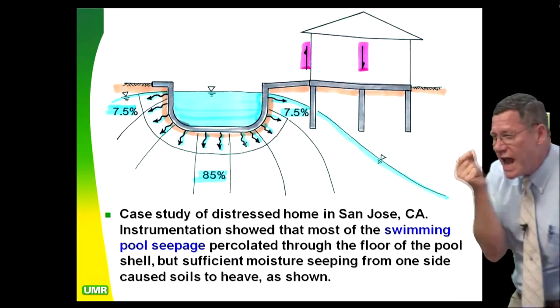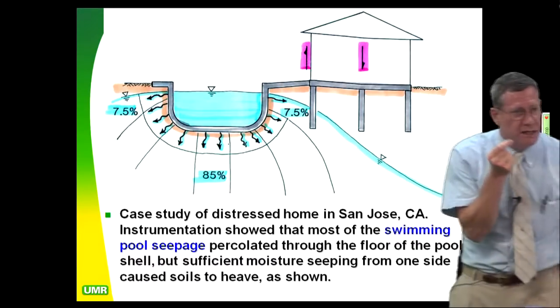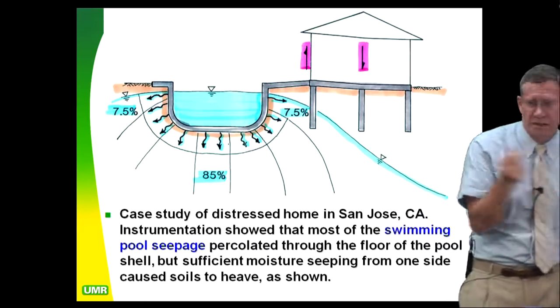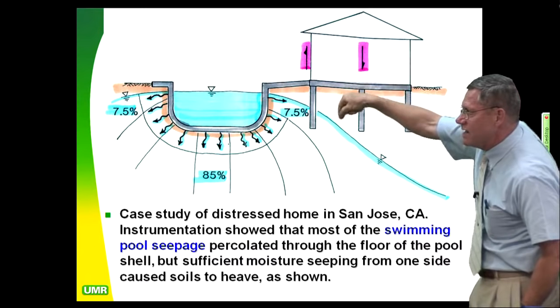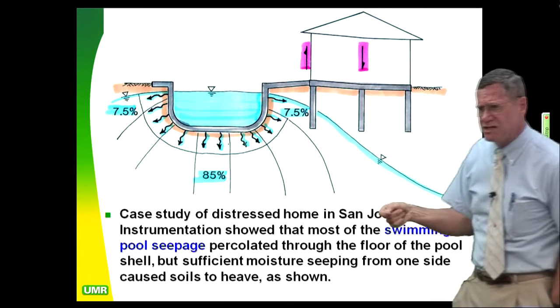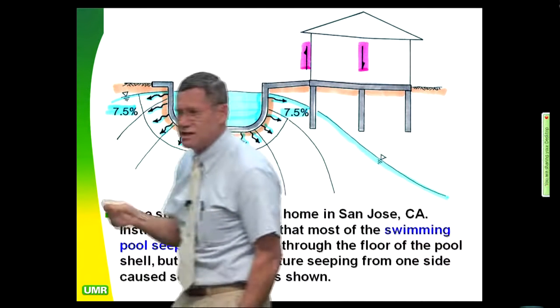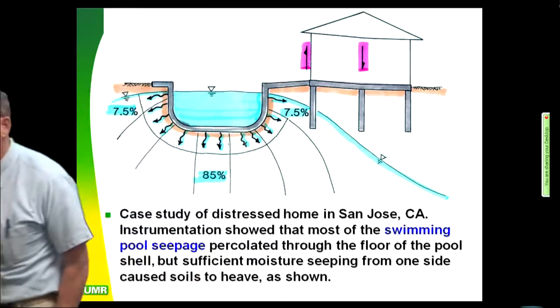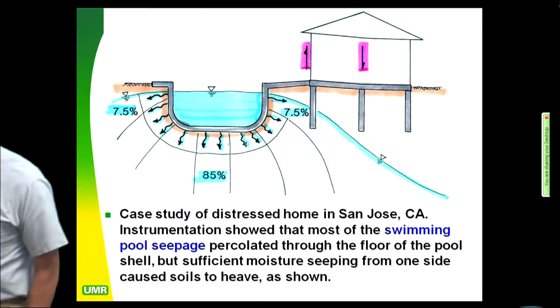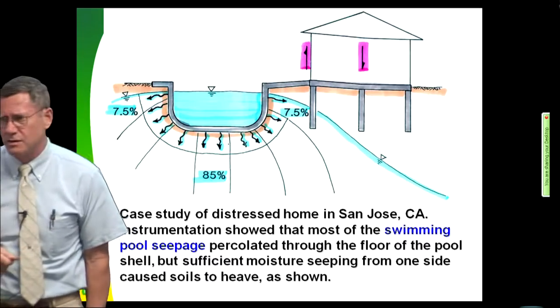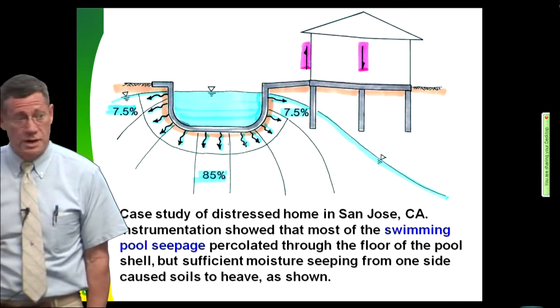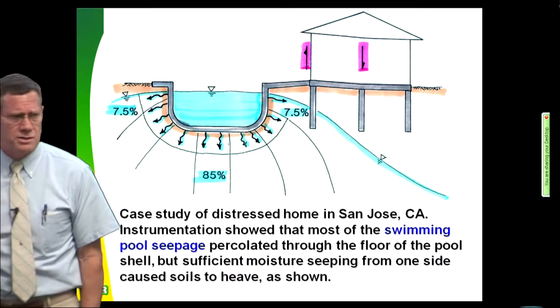It's the most accurate tool in your tool chest for seeing the zone of saturation when you're out putzing around structures. Because as soon as you hit the saturated zone, you'll see a 6 to 8 degree change in 1 centimeter. Boom! You know right where it is. You put a piezometer out there, you have to instrument it for 3 months to find out where it is. Takes forever, the piezometer. Cone pen is great on seeing the zone of saturation.